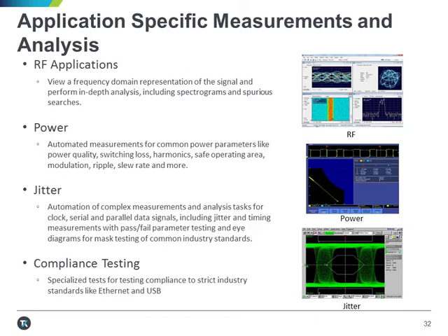We've already talked about RF applications a bit in reference to the MDO, but if you're working down into the very nitty-gritty of signal integrity for digital communication, you may want to look at scope applications that can demodulate high-speed signals, display the spectrum and spectrograms, and pluck out symbols from the data stream itself. These applications generally make sense only on oscilloscopes with bandwidths in the multiple gigahertz ranges.